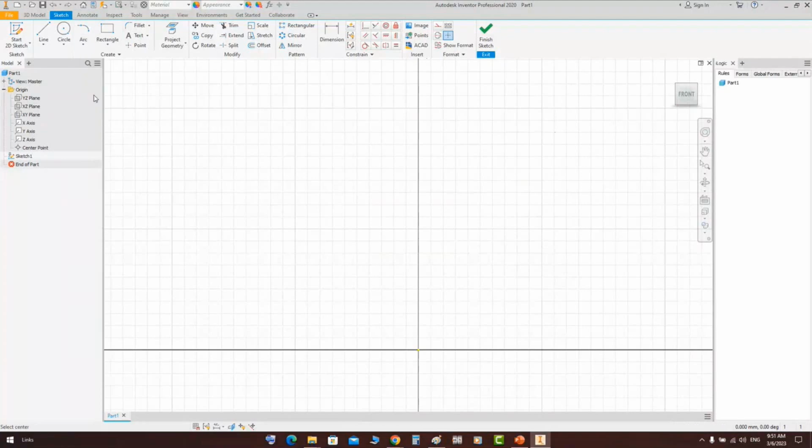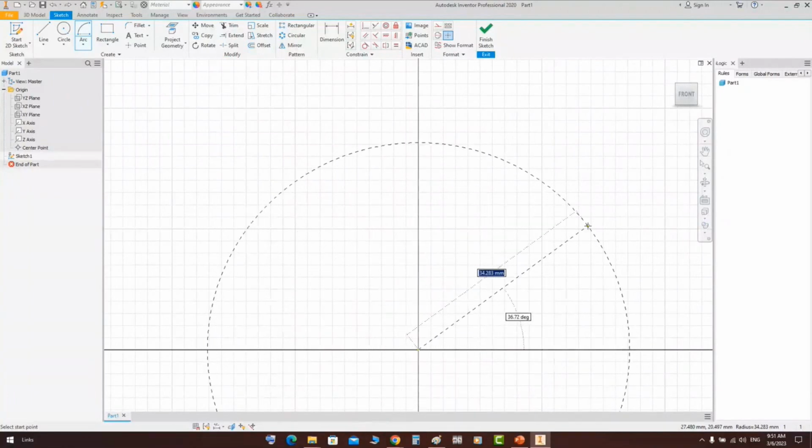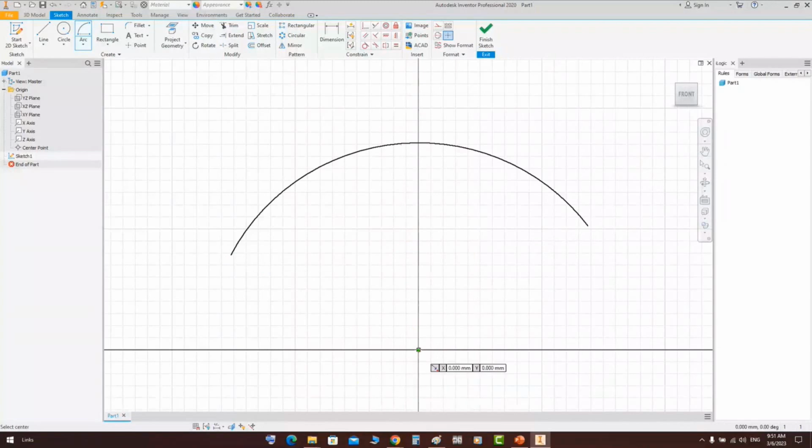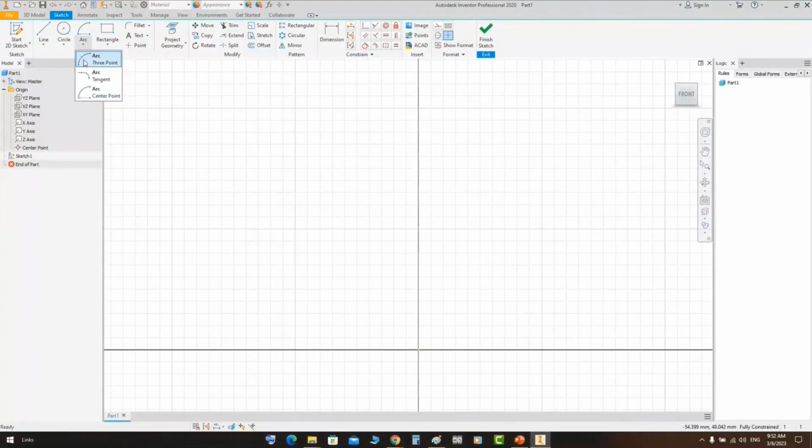The third type of arc is like the tool that you use to draw a circle in real life. You will open it and define the center point. After that, define the diameter and start creating the arc that you would like to draw, which is called bargal in Arabic. So you can make it like that. So define the center point, open the tool and draw the arc in the directions that you would like to draw. Okay, that's the third way to draw an arc.